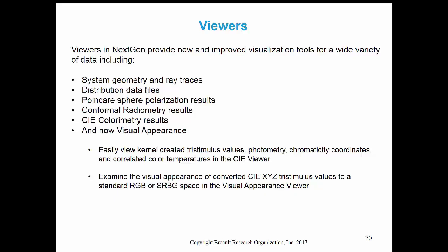CIE automated photometry and colorimetry simulations as a function of illuminance, luminous intensity, and luminance previously were added to the computational kernel. This included automatic polychromatic source creation with sources based upon black bodies, CIE illuminance, user apodization functions, and tables.